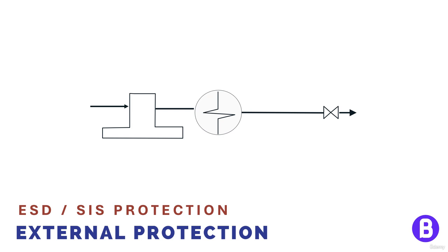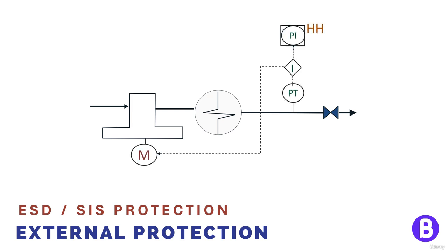Or if we are having a positive displacement pump, which doesn't have a shutoff pressure, unlike the centrifugal pump. So in case some blockage occurred in a positive displacement pump, for example, if this valve was closed, we shall need to trip the pump at a high pressure signal.